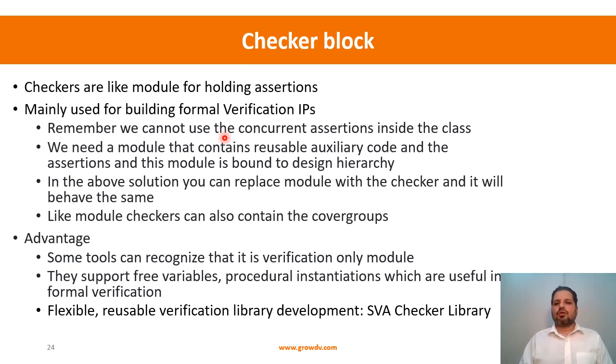The same thing, you can now replace that module with the checker. Instead of saying module and some name, you remove module and put the keyword checker, and it will all behave the same. Like modules, checkers can also contain a covergroup, so if you are implementing coverage, it can have the covergroup as well.